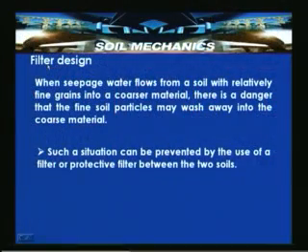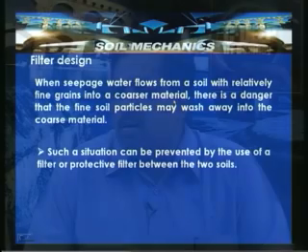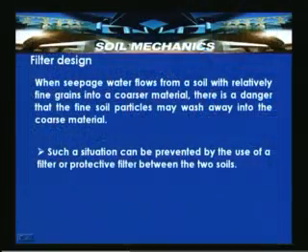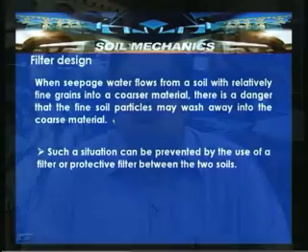How can this filter be designed? Before looking into different aspects: when seepage water flows from a soil with relatively fine grains to a coarser material, there is a danger that the fine soil particles may wash away into the coarser particles. When the fine soil material washes away into the coarser particles, clogging can take place. With that, hydraulic pressure will build up, and again it endangers the performance of a structure. Such a situation can be prevented by use of a protective filter between the two soils.